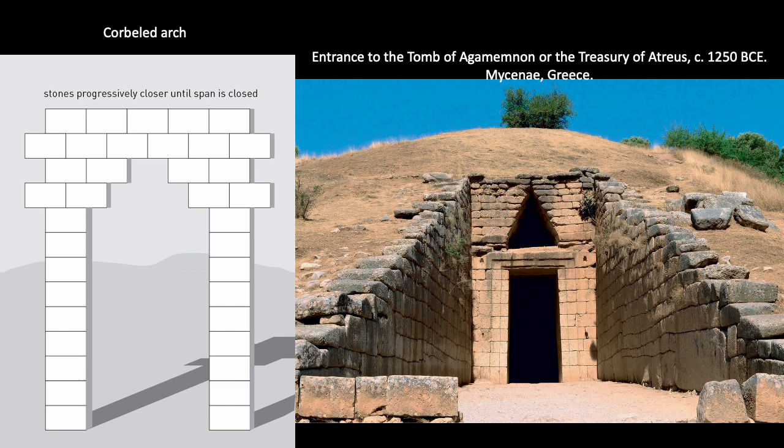That's what cantilevered means. This sort of successive stepping inward of layers of stone over a doorway allows for the compression created by the weight of the building to be directed outward through those cantilevered stones and then downward through the upright posts or the load-bearing walls, rather than acting straight downward on the unsupported center of the lintel. This system really reduces the pressure on the structure and allows the architect to span a larger